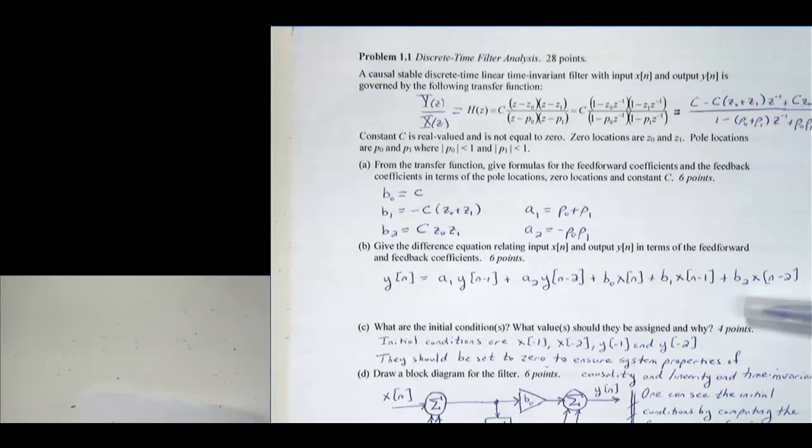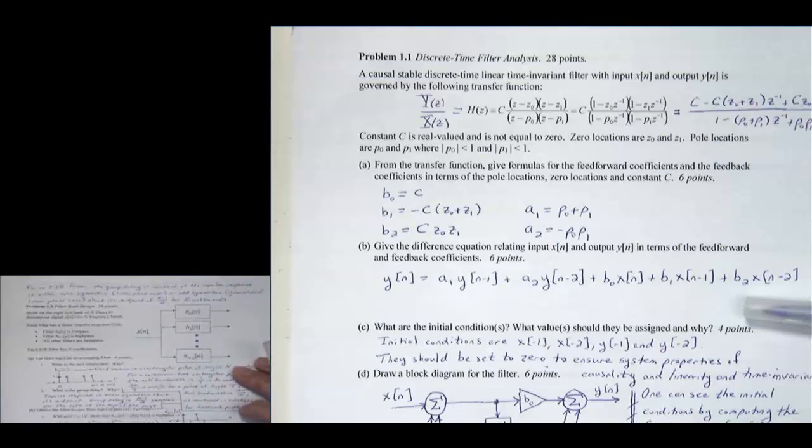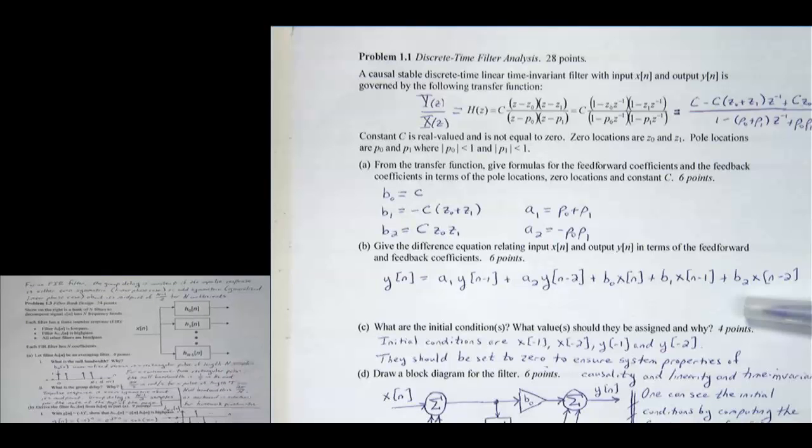All right, problem 3. This was a really tough question. I will tell you, this is a tough question. So part of this is, all right, so why did I ask it? This gives you a very quick way to design an analysis filter bank from one filter. That one filter, in this case, is a low-pass averaging filter, but it could be any low-pass filter. It could be an FIR designed from Parks-McClellan. It could be a Hamming window. You start with one simple low-pass filter, and we can build up a way to do essentially a spectrum analyzer.